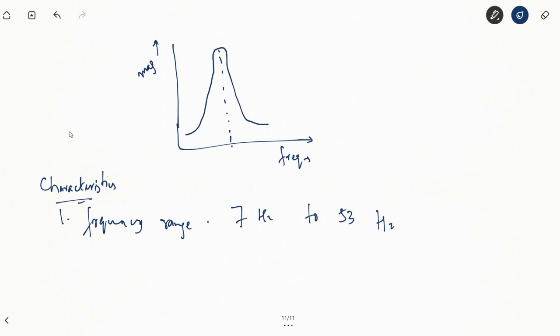So we have one reed that has the most amount of vibrations, and knowing its natural frequency of oscillation, we are already aware of the natural frequency of all the reeds, knowing their size and their weight.